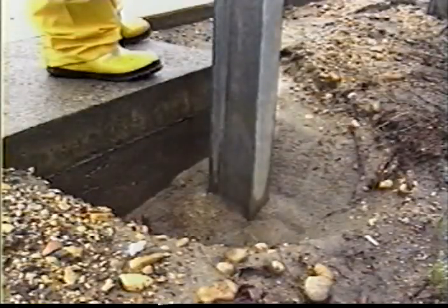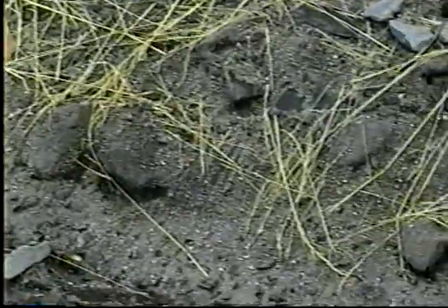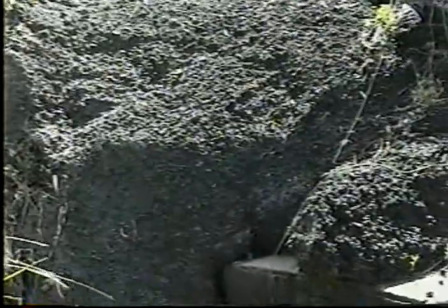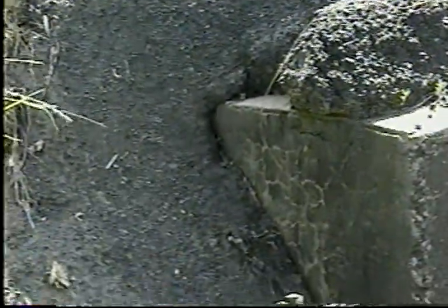Scour around footings, cut-off walls, and head walls is repaired by replacing the eroded material in kind or by filling the void with riprap or sacked concrete. In an emergency, a bituminous mix may be used.